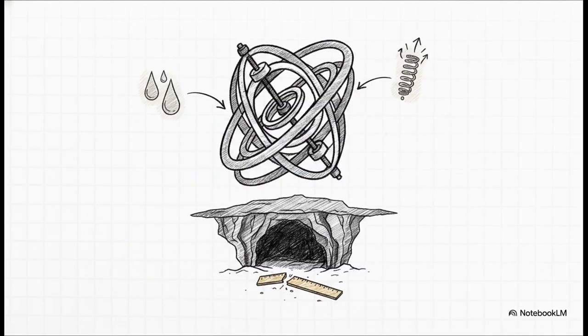But wait, remember our z-factor? As the pressure drops over time, that z-factor, along with the gas viscosity, is constantly changing too. So to solve this for real gases, especially in deep, high-pressure wells over 3,000 psi, we have to ditch those simple approximations. Instead, we use the brilliant Al-Hussainy and Ramey real gas pseudo-pressure function. It's an absolute mathematical powerhouse that continuously accounts for that shifting viscosity and compressibility, completely preventing massive forecasting errors.